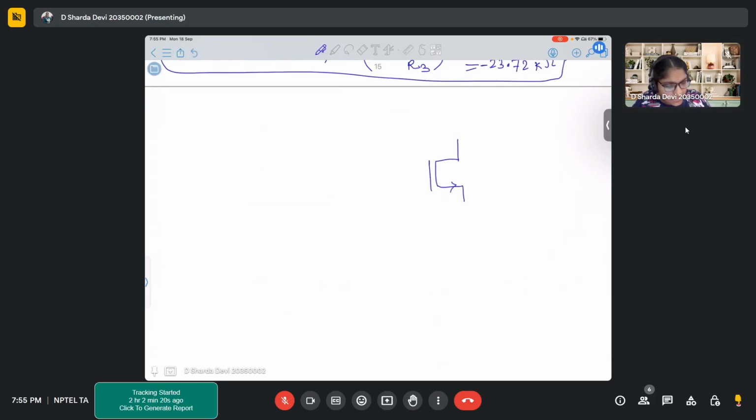So your PMOS, you were saying. Okay, let's say you have a PMOS and you want to write GM, correct? So how do you write it? Like GM into VSG plus GD into VSD, correct? That's the basic formula. And we are saying that it is in diode configuration. So GD, that's right. So ID will be GM.